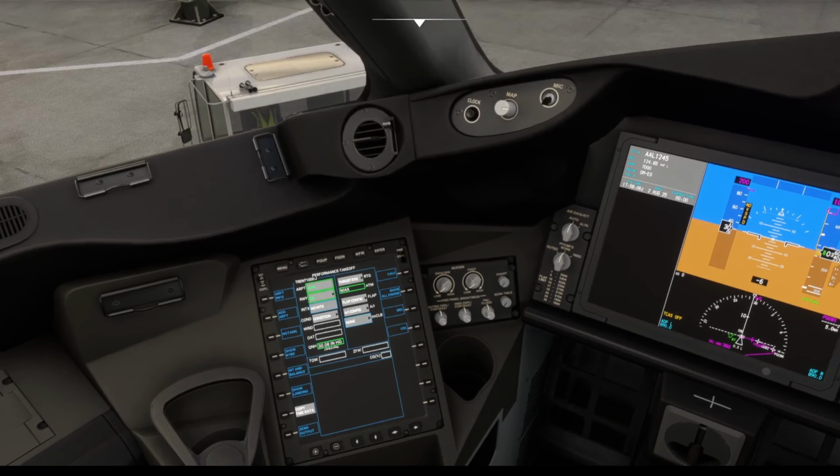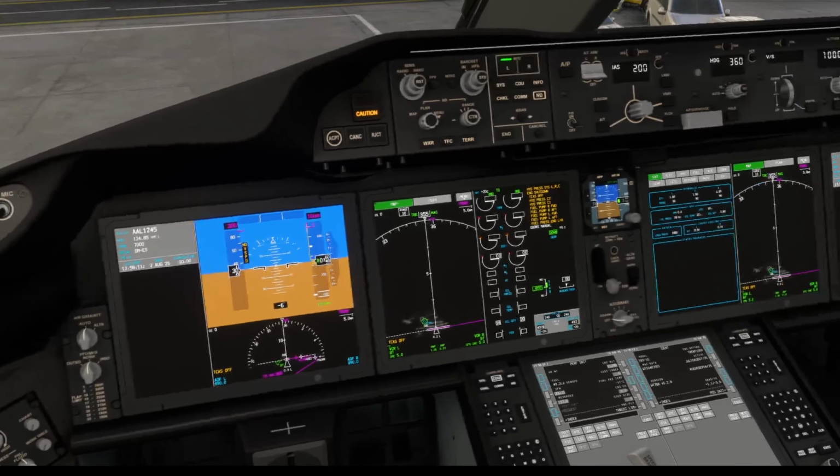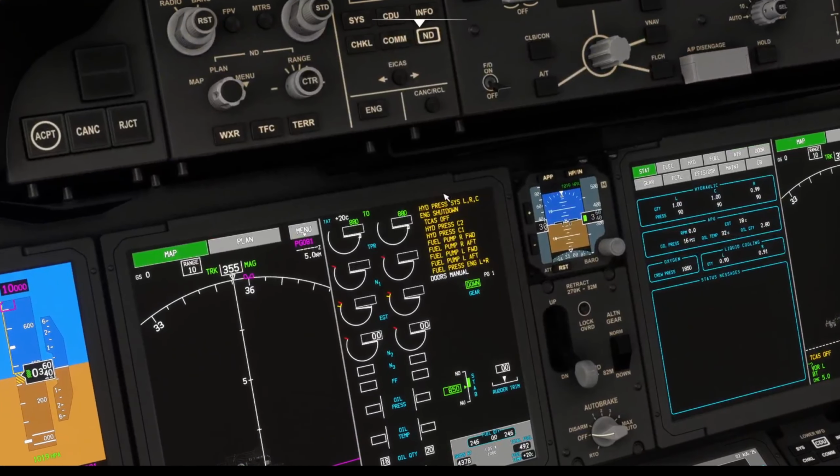So yeah, you can adjust your lights here and just make sure that everything is normal. Cancel this, and you could actually go through all the messages. So yeah, something like hydraulic pressure is obvious since we have all the hydraulic systems shut off at the moment. We don't need them right now. Engine shutdown, it is pretty self-explaining. TCAS off. Yeah, and here we go again. Hydraulic pressure, center 2, center 1 pump, and fuel pumps, basically. Fuel pressure left and right engines, yeah. This is all expected.